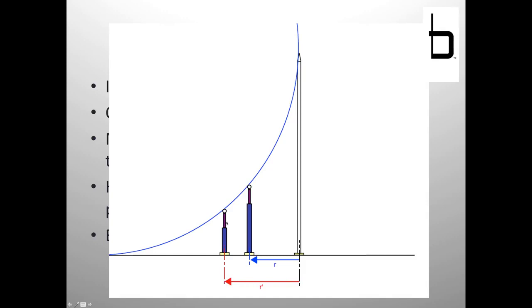Right. And this is also important because as you protect a substation, you're going to have several different equipment heights. Some equipment may be 20 feet, some other equipment may be 30 feet. So you really should do a protection calculation for different heights. Now, if you choose the highest point of your substation, let's say 30 feet is the tallest bus that you have, and you're able to protect your entire substation,